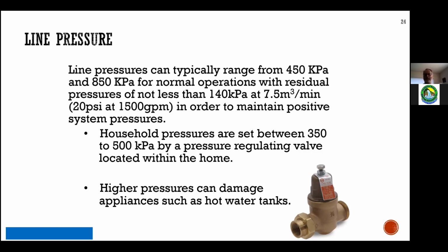So there's this balancing act between creating enough static pressure, static head and elevation, and designing the system so you don't rob it of that energy along the way. But if you have excessive elevation changes, you don't want to overpressurize the low areas, and you don't want to underpressurize the high areas. So we'll talk about ways of doing that, whether it's pressure regulators or altitude valves or pumps as we go into operations. But it's all tied to the same concept of elevation creating head, static head.